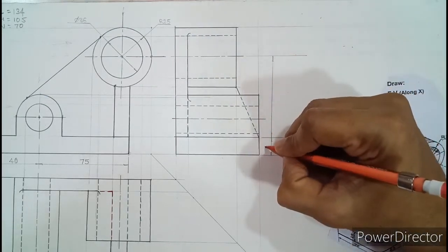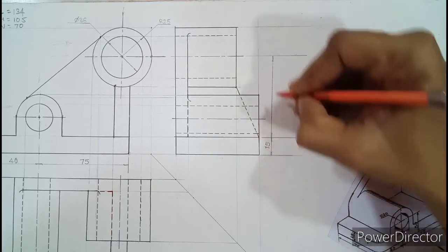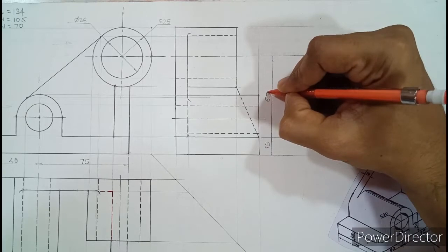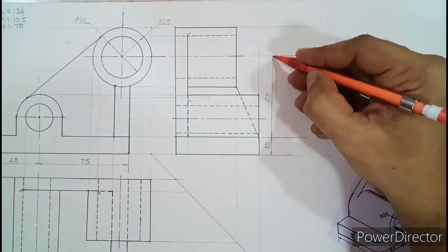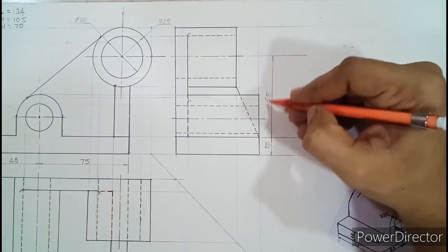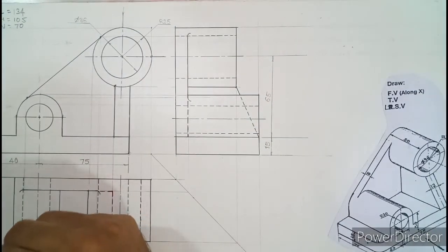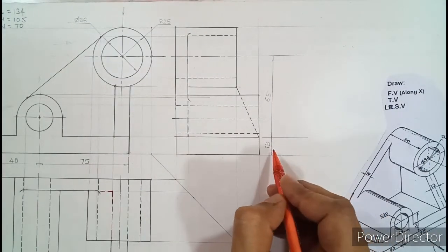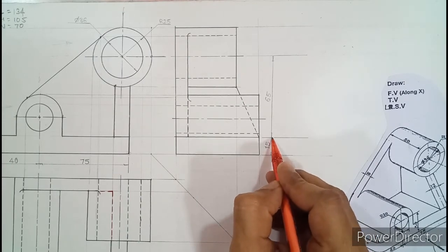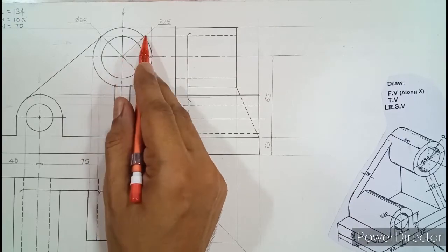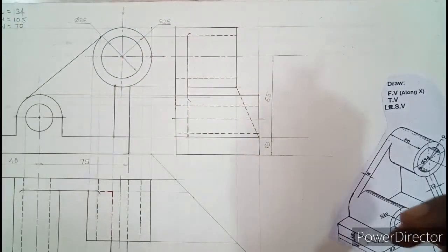So this is 15 and here it is 65. When you write this 65 and 15, try to write approximately in the center of this line, not right or left. Now when the reader wants to find the height, it can be done as 15 plus 65, then project here and add radius 25. So that is how you get the total height.